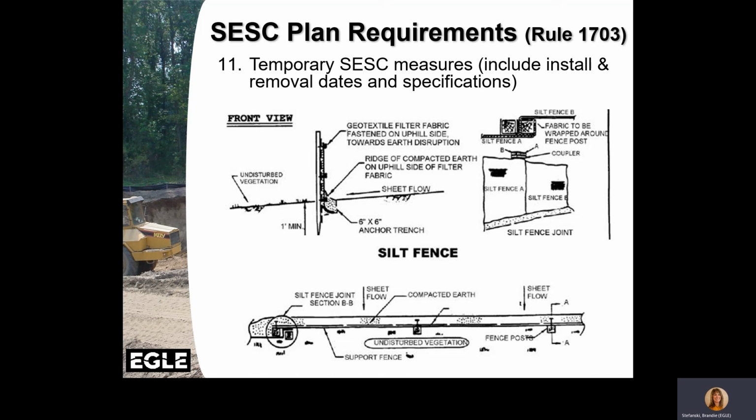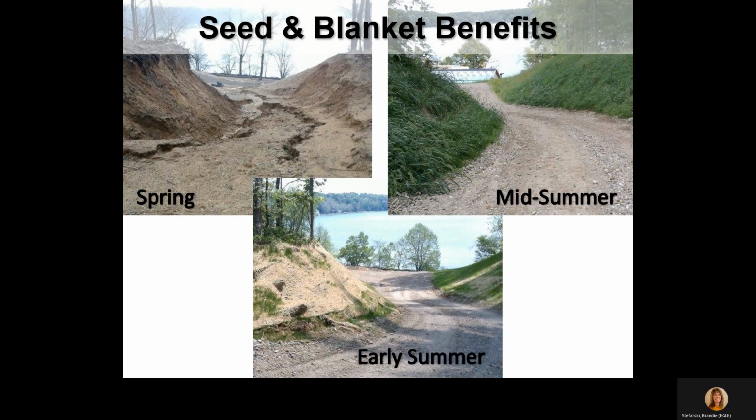These are questions that need to be considered. This is an 8-acre site with steep cut slopes and no plans for seeding or blanketing until the end of the project. Several discharges were documented to the list. Should this plan have been approved in the first place?